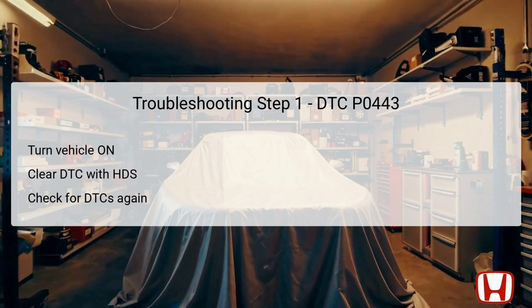After clearing, start the engine and maintain idle at 3,000 RPM until the radiator fan activates, and then let it idle. This process helps create a situation where the EVAP system can be accurately assessed. Finally, check for any new DTCs to confirm whether the initial issue persists or if it was a temporary fault.